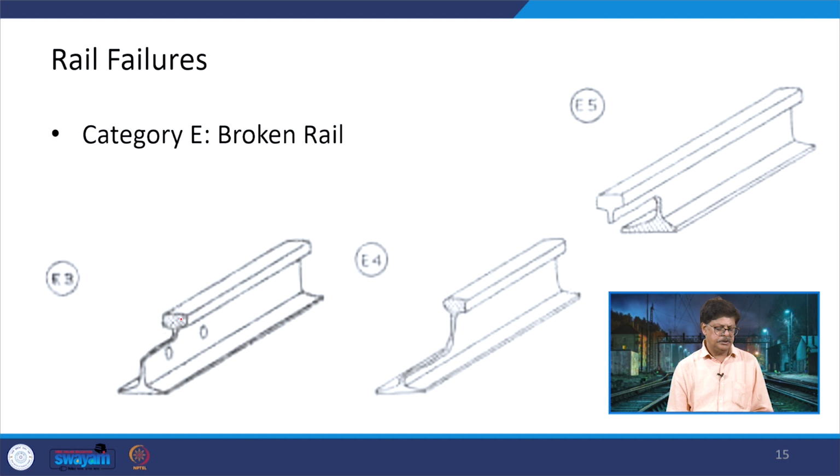Then another one is where not only the head has broken, but it has also taken away a certain portion of the web. So, probably there is a propagation in the web, as we have seen as a D, and then a transverse propagation up, which has moved in either direction, and finally when the load came at this portion, it broke down. This is a case where it happened above the bolt holes, but in the other case, you can see it is much more enlarged and has taken up the total section here, including the bolt holes. So, a total big failure is there.